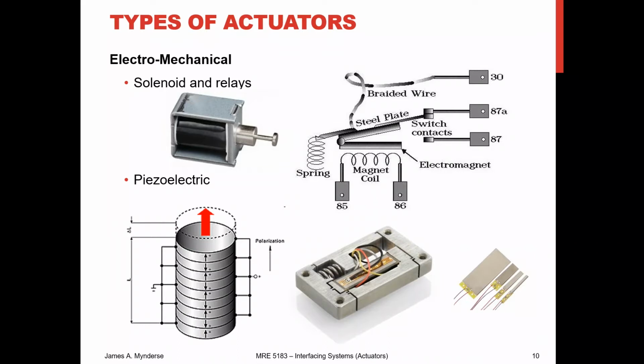Piezoelectric is something that I've dealt with quite a bit. Piezoelectric materials are going to respond to a charge. We'll apply a voltage usually, but they are going to expand or contract in the presence of a charge. That's the actuator side. Certainly remember, a piezoelectric material could also be used as a sensor, where it is going to turn a compression or an expansion into a charge which is measurable. So on the actuation side, you're going to apply this voltage and then you're going to get motion.